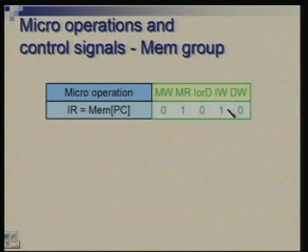This controls writing into IR register, this controls writing into DR register, and one operation is fetching the instruction. So, we are not writing here, we are reading, it is an instruction, and the multiplexer code for that is 0. The value which is being read is written in IR register. So, we keep this one, keep that 0.